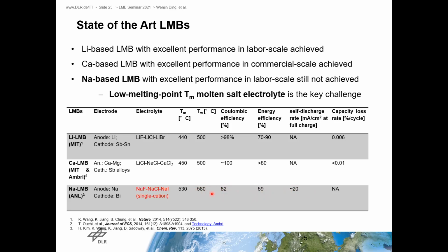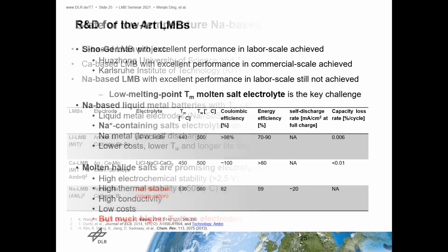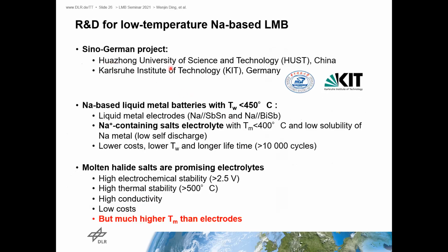From our heat storage experience, we think that if the temperature is higher than 550 degrees C, we need to use expensive alloys. So in our project with our partners in China and Germany, the Huazhong University of Science and Technology and KIT, we want to develop a low-temperature sodium-based liquid metal battery. Using sodium can reduce the battery cost, and low operating temperature can reduce the cost of the structural materials.